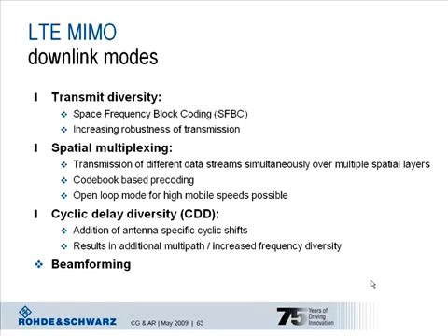An additional scheme used in LTE is called cyclic delay diversity. It is used in addition to spatial multiplexing as a further enhancement. An antenna-specific delay is added to the signal transmitted by each antenna, delaying the signal effectively, and this is done by a cyclic shift of the signal on each antenna. This effectively results in an artificial multipath situation experienced at the receiver side, causing an increased frequency diversity effect. Finally, beamforming can also be applied in LTE, which is especially relevant for the TD-LTE part.